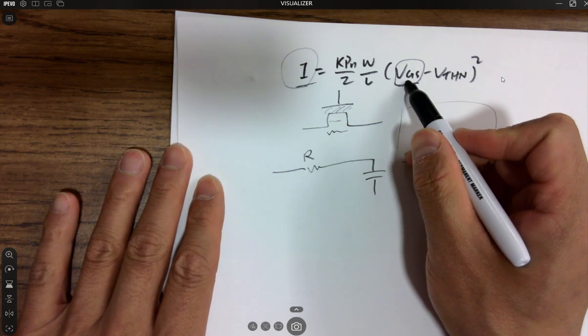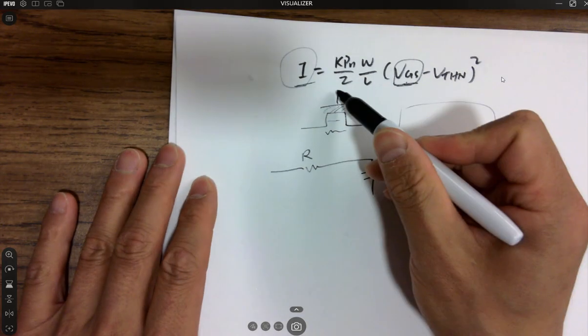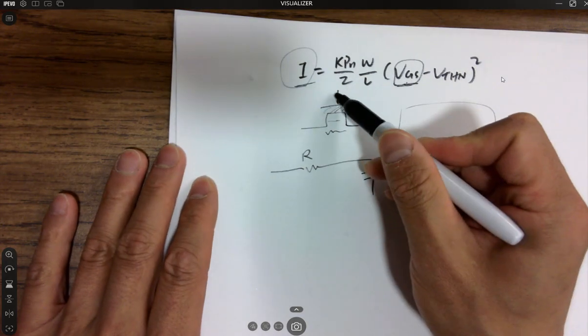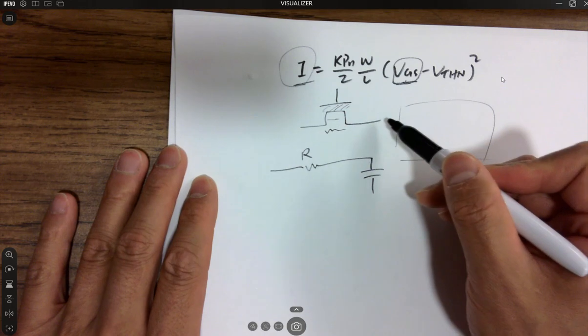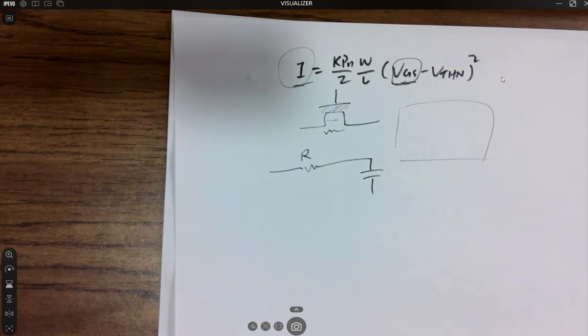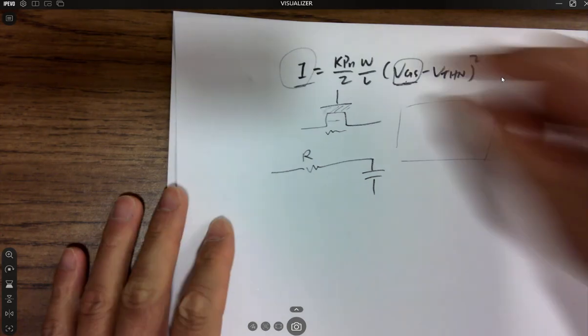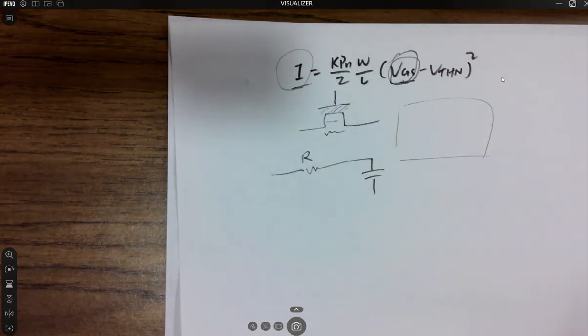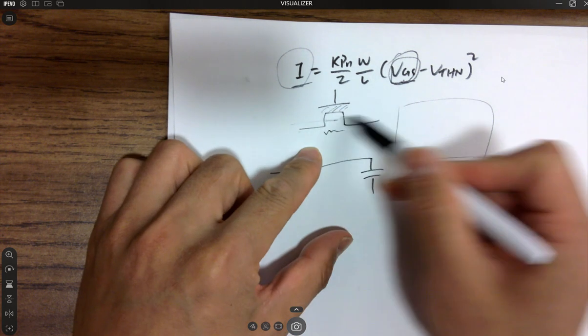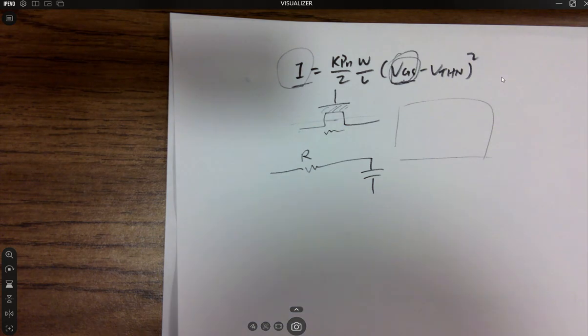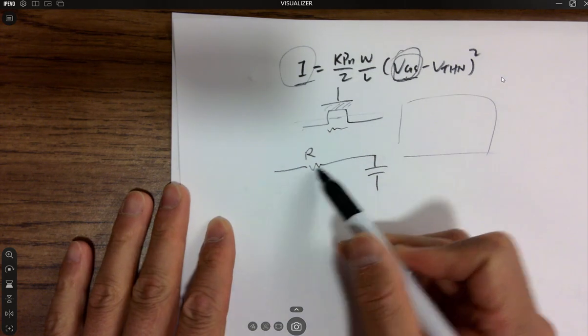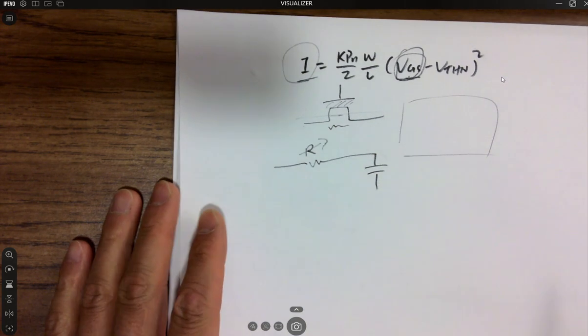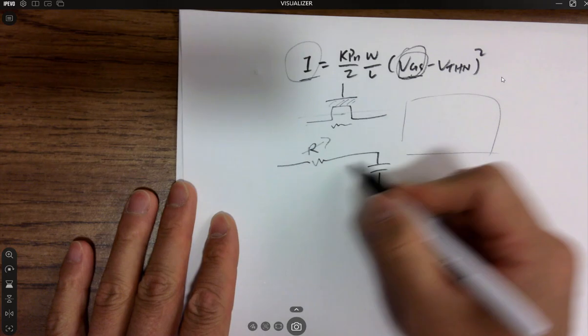The way to understand this easily is that it's like a faucet, right? If you turn the faucet fully on, there's a smaller resistance in the channel. Because if you give a big VGS, you turn this fully on, and it's able to run water through it easily, right? If you model everything like an RC circuit like this, R is going to change. As R is changing, your time delay is changing.